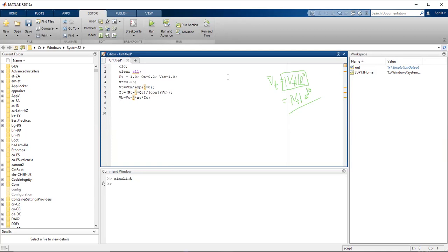Then we said we will locate the Q axis by calculating some EQ phasor, E capital Q. How did we do that? We took VT plus J into XQ into IT. Now we don't know XQ, but we said this should be given. Let's take 0.6, any value. Remember, these are arbitrary. I don't know whether they are meaningful or not, but I'm just taking it for the sake of demonstration. So EQ is VT plus JXQIT. So Q axis is located.